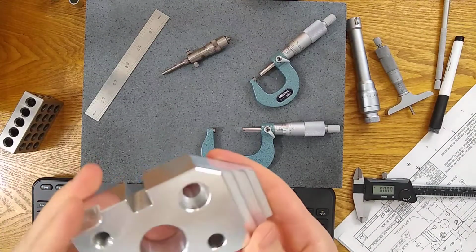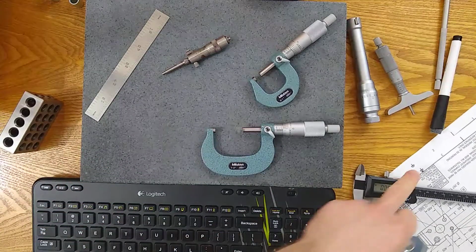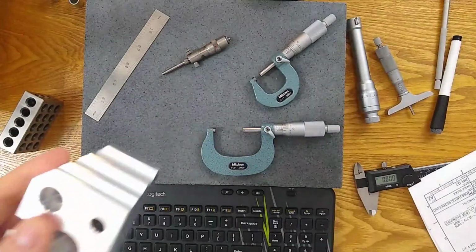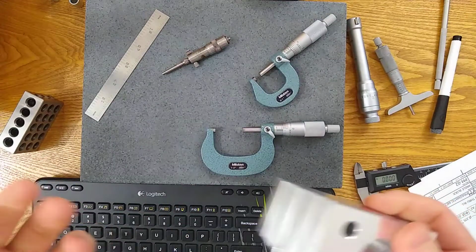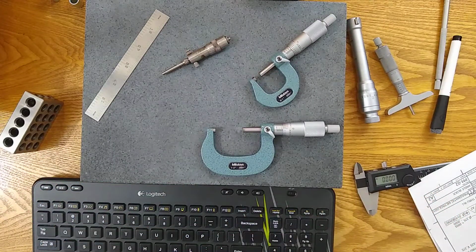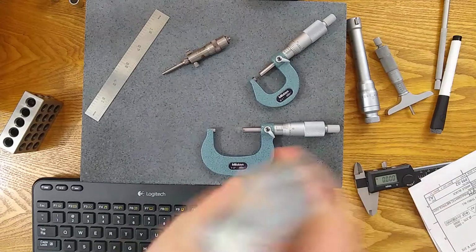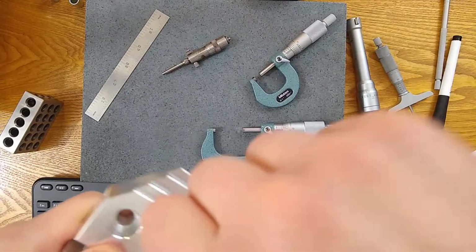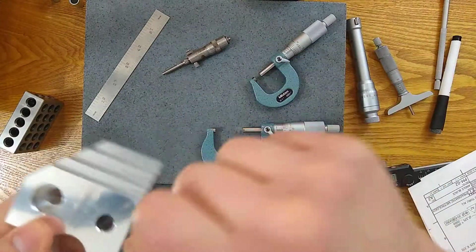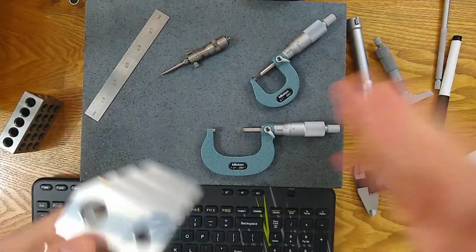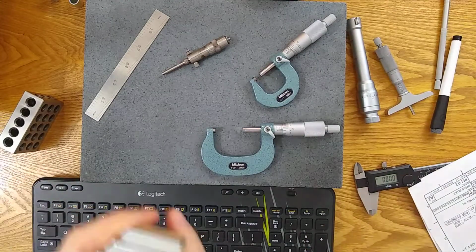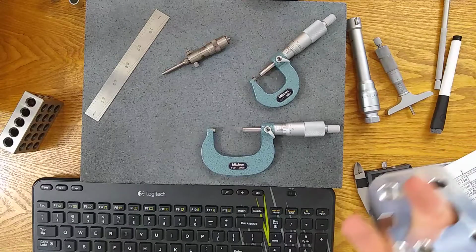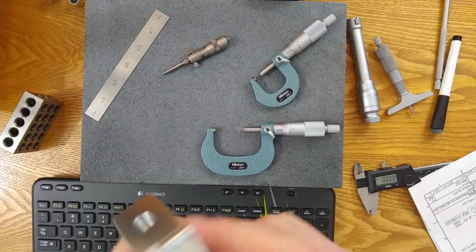You've thought about the gauge you're going to use, the accuracy, the tolerance zone. You've inspected the surfaces you're going to use and said they're good, or maybe they're not, but you have to try. So now, number 6, was the measurement a good one? Do you feel confident in it? Do the anvils get good registration, solid, repeatable, or were they rocking? Were you twisting, so you could get any number you wanted because maybe there's some taper, some form error? Did you get good pressure? Is it repeatable?